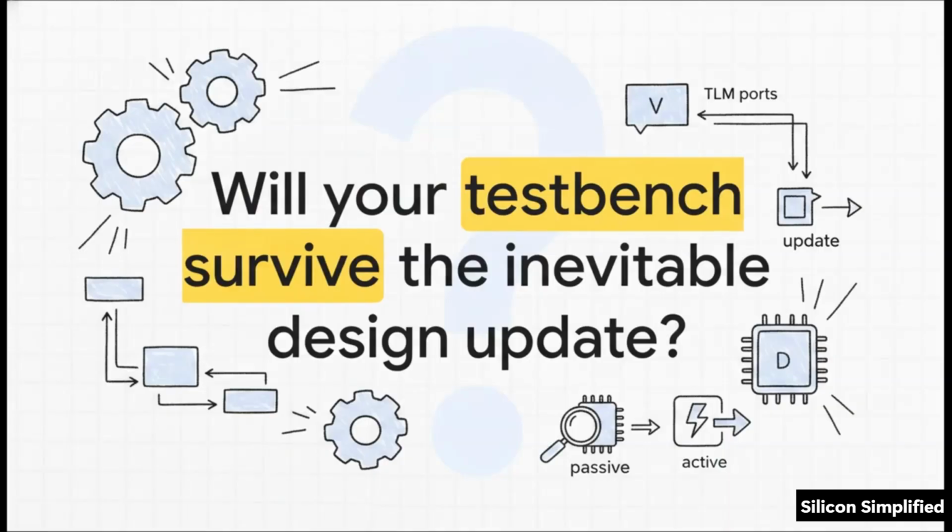So I want to leave you with this final thought to really challenge how you approach your next verification project. Your design is inevitably going to change. Will your test bench survive the update? The core principles of the UVM agent, strict encapsulation, standard communication through TLM ports, and those dynamic active and passive modes, they ensure your test bench doesn't just survive an update, it scales effortlessly right alongside your design. Start leveraging these concepts, build your verification IP modularly, and for goodness sake, stop reinventing the wheel.